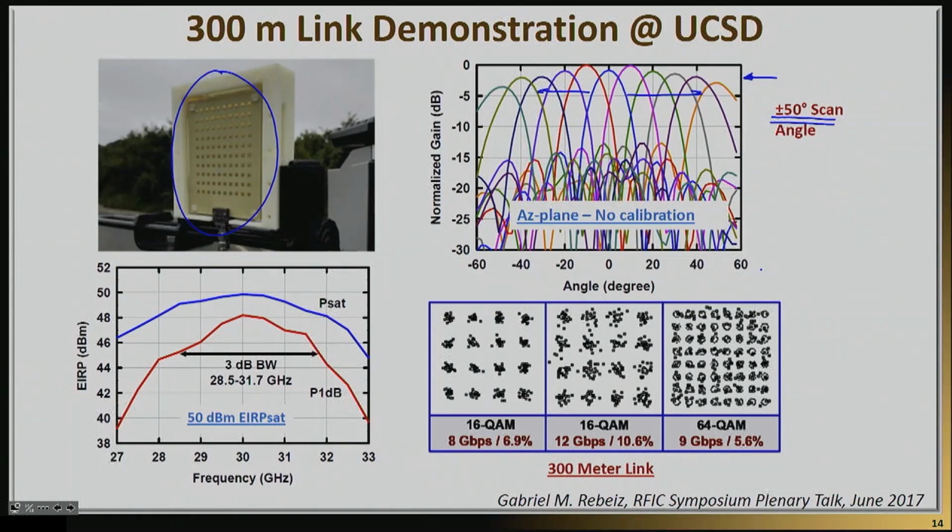First of all, notice the side lobe level. So side lobe essentially is the next lobe next to the main beam. You can see, for example, here in this line, the side lobe level somewhere here is in the order of 15 dB. Most of the side lobe levels here are between 15 to 20 dB. Now, that is actually a direct result of what I was mentioning before, this uncalibrated performance. The reason you have the side lobe levels and you can't bring them down to, let's say, negative 30 dB is because there is a little bit of a phase error when you add or subtract the paths, and that phase error cannot be corrected if you do the uncalibrated performance.